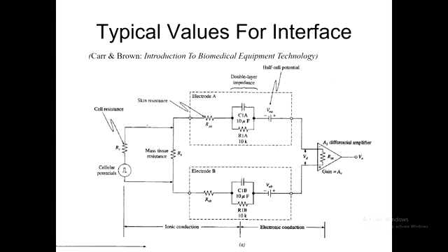And then I'll give you a hint. One thing you can do is imagine that since you'll have a loop with two RC networks in it, and the loop is connected by a couple of R's. Here's one that turns out to be a big value of R, and this one's a small value of R, but they're in series with each other in effect. You can put them together as one resistance in a big loop. Can you see that?